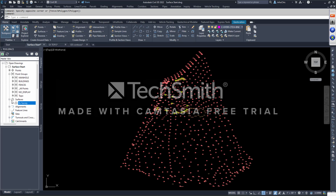Okay, anyways, back to the top of our file. Open up the surface start. In the surfaces collection, expand the existing survey object and expand definition. Now, if there was something in the model, you could have selected anything in the model if it was already in the surface, and this ribbon up here would change. But right now we don't have anything. So let's put something in our surface.